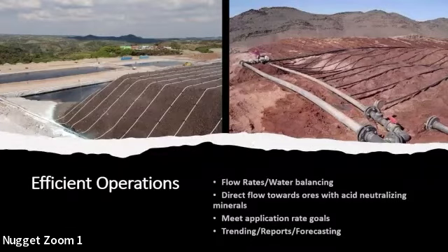So here's an example of a flex wall cell where on the left, we consolidated it to what would be equivalent to 10 feet below the surface. On the right is equivalent to 30 feet below ground surface. After doing the consolidation and the work, we froze the cell and extruded it so that it looks like this. You can see with the 10 feet on the left some pore network, which you would expect to translate into higher permeability conditions. On the right, which is again 30 feet, you see a reduced pore network visually, and so reduced permeability of that ore material would be expected.